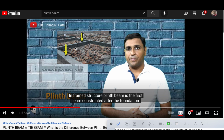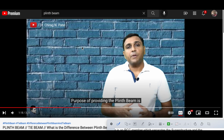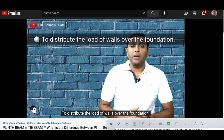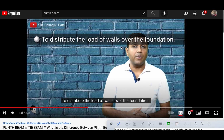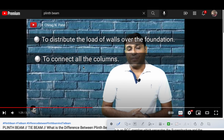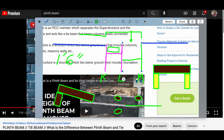And the intentions of what it does down there is the same intentions it does up where we are on the first floor. My opinion. The purpose of providing the plinth beam is to distribute the load of walls over the foundation of the building, to connect all the columns. Remember, if you lose one of them, we gain in that torsion, that rotation that can happen.